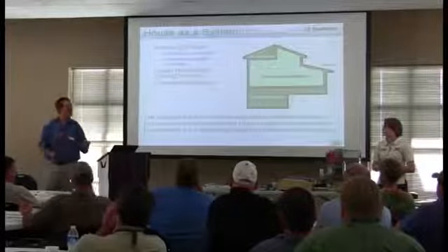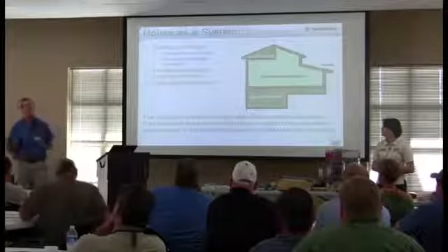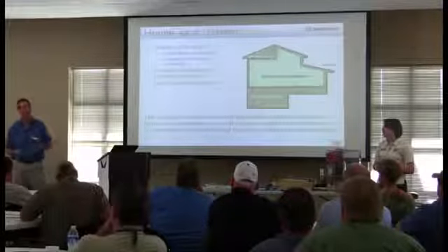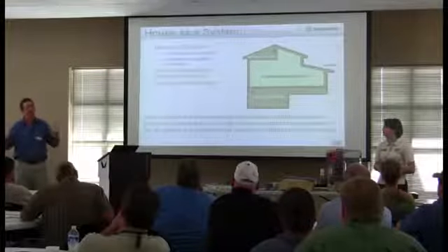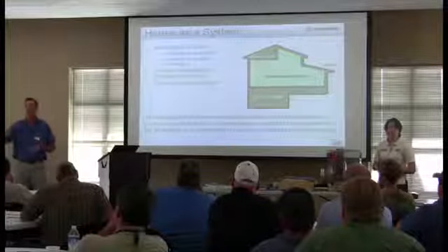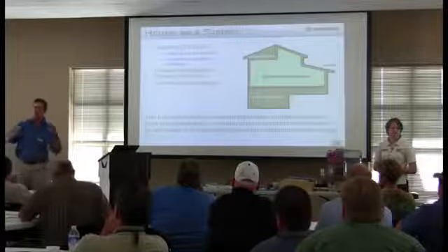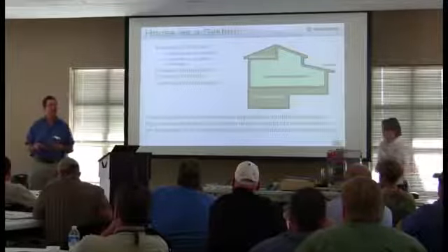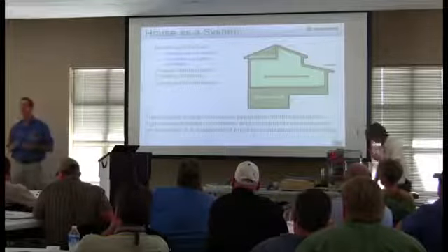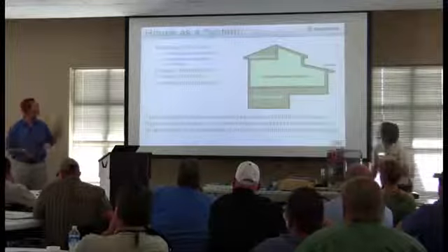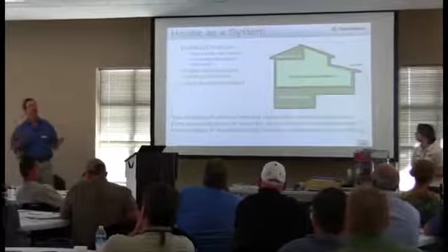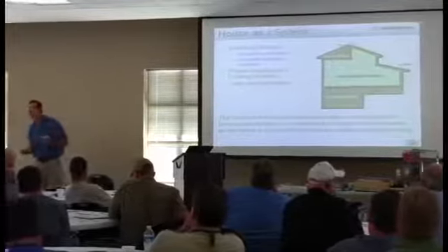And if we have time, we'll show you very quickly a couple of ways that we do this. We do this, by the way, on just about every EarthCraft house. Every green building program, every beyond-code program is all about sealing up the house, because that saves tremendous amounts of energy. And then bringing in intentional outside air from a known source, and that's for health reasons. So it's kind of winning the game. You get the best of all worlds if you do both of these things.